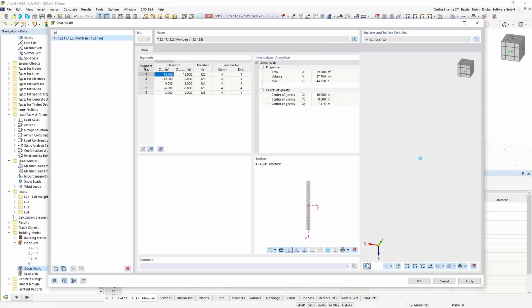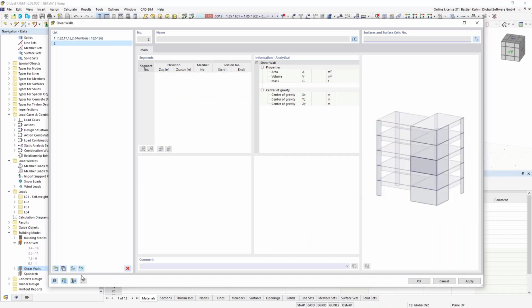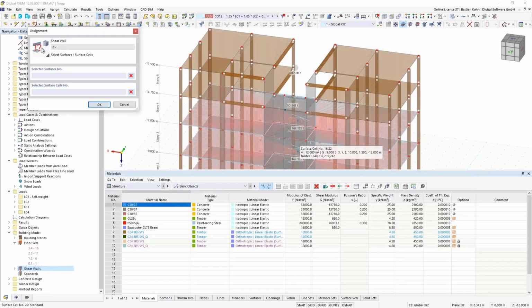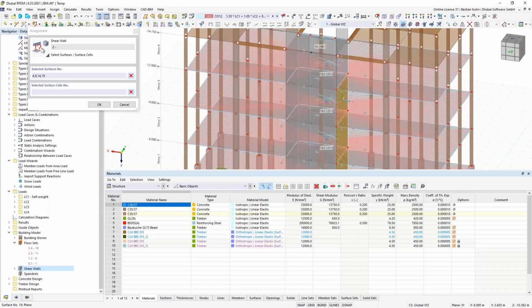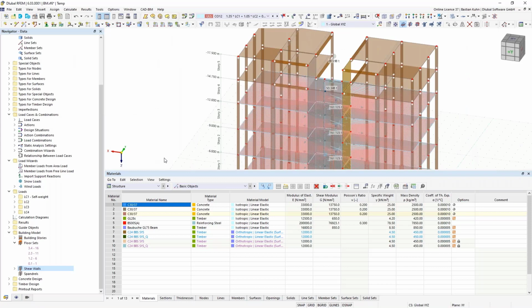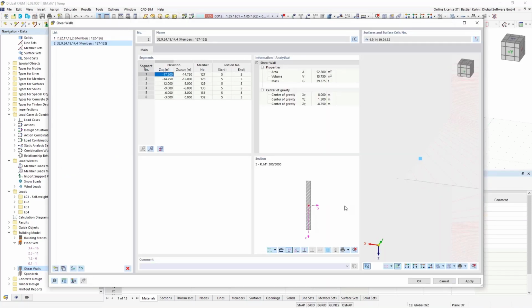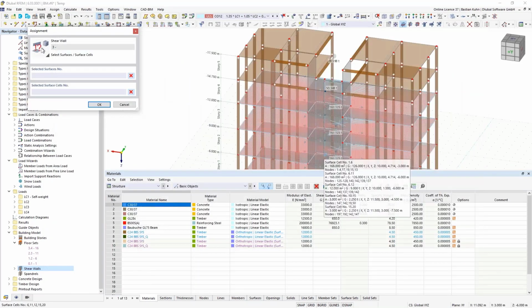Should have switched on the rendering, because now you can see what it's doing there. It's generating a section that goes from the first story to the fourth story. And I'm doing the same for the sides, as those walls are going from the first to the fifth story. And then also the opposite side, I'm doing the same.